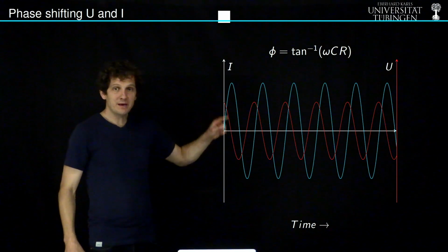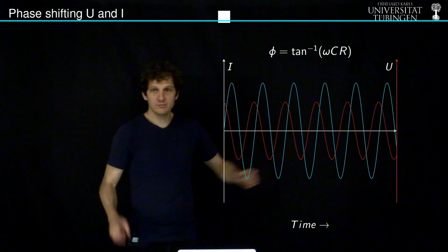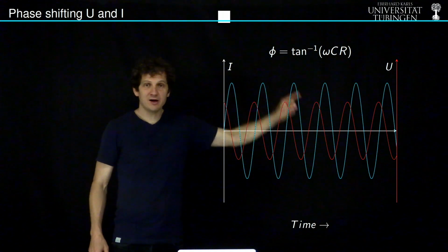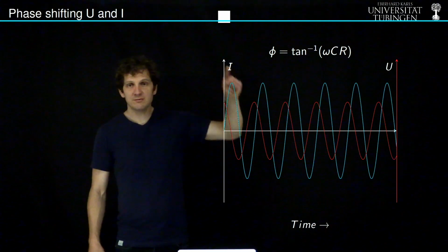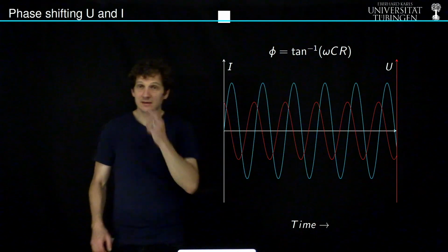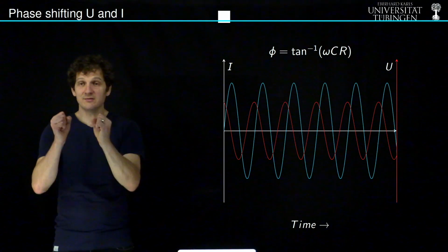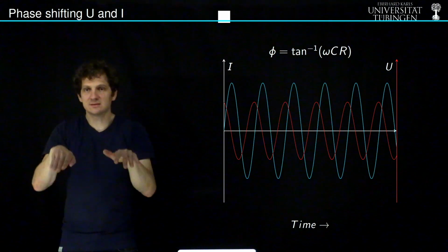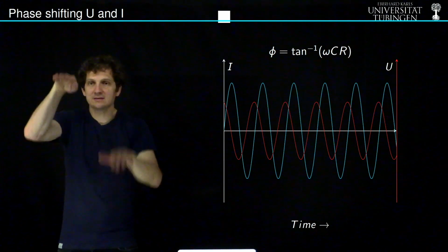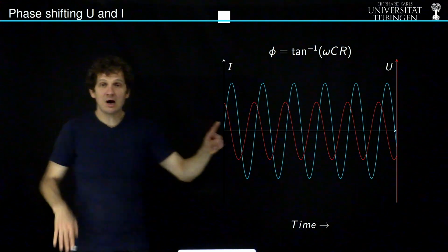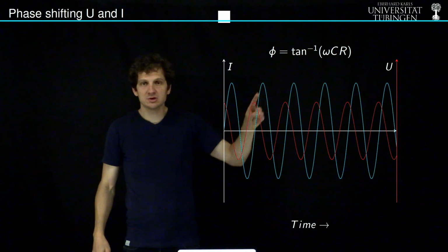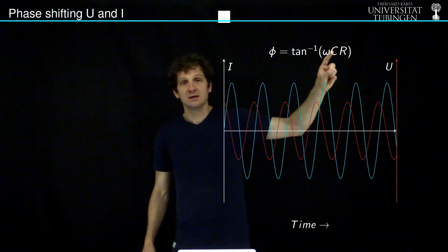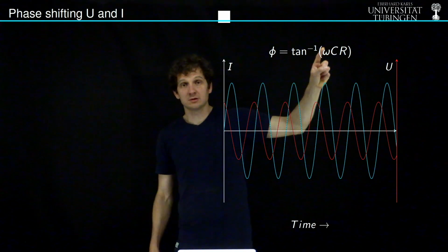So remember, we measure the potential drop at the surface with our electrodes M and N, and we induce the current at the battery, and now we are in this time variable regime. The current that we induce is the blue curve, and the potential drop that we measure, if capacitance is relevant, will be out of phase, meaning those two curves will not be in phase. This is the resistivity method, but they will be out of phase, and the phase shift corresponds to the shift of those maxima here. The degree of how much they are out of phase depends on a number of things, but it definitely depends on the possibility of the material to polarize, C.